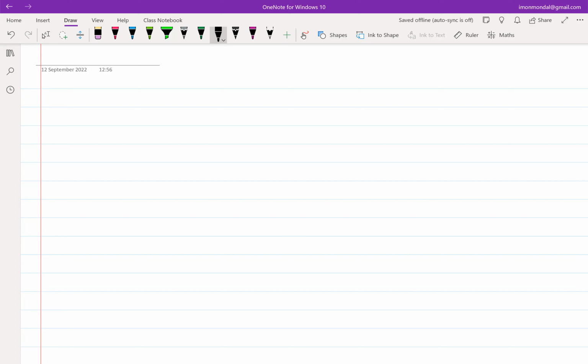So with that perspective in mind, we were delving into swing limits from the idea that ultimately this will be an amplifier, and an amplifier will have large gains, which means it can have a large output swing for a given input swing, which by definition means that there will be certain MOSFETs which will tend to go out of their safe region of operation and go into either cutoff or triode, right?